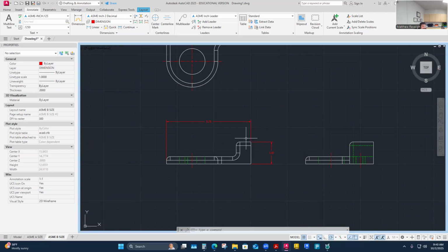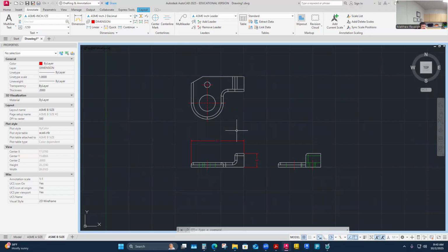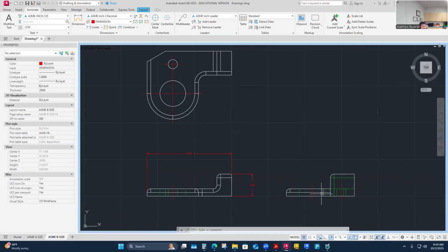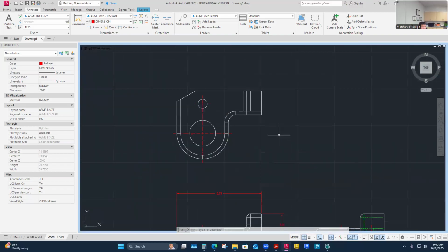But you always have another good option of a center line as a datum. But there's two, and then I just need the depth. So it's almost like I'm going to establish another datum to go to the depth. I can't use it here, but I can definitely get it in the top view, or I could get it in the right side view. And to me, I don't know which one is better. I really can't tell right now which one is better to define it.